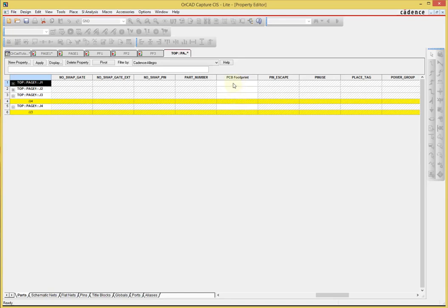What we need to write in here is a footprint name. Of course, we need to know what that footprint name is. Many professional EDA software tools provide a rich library of pre-made footprints of commonly used devices that you can enter here as a designated footprint.